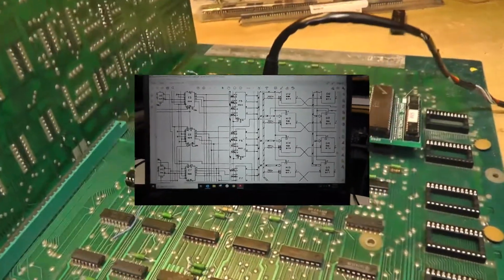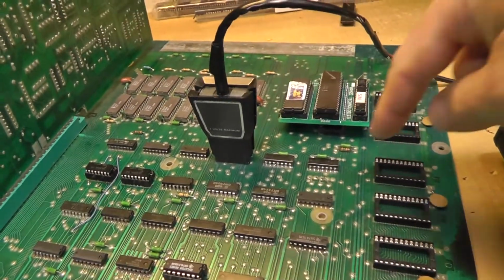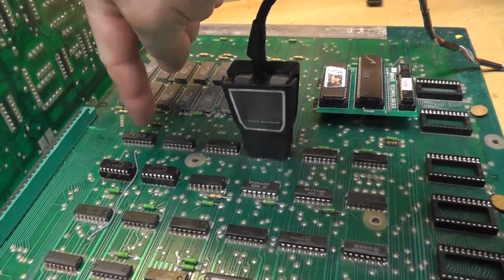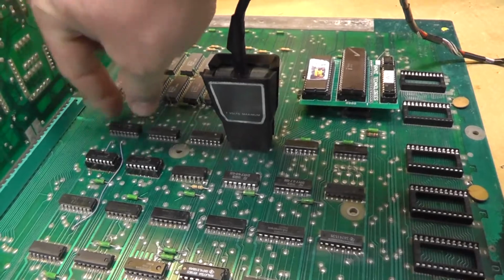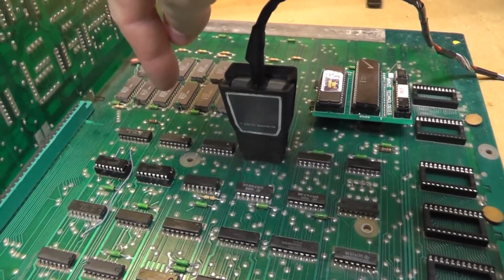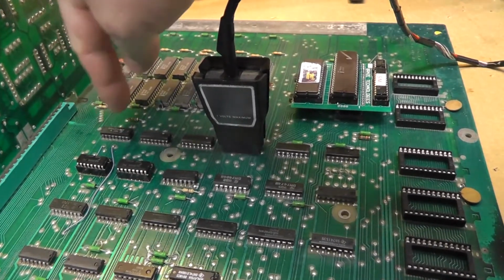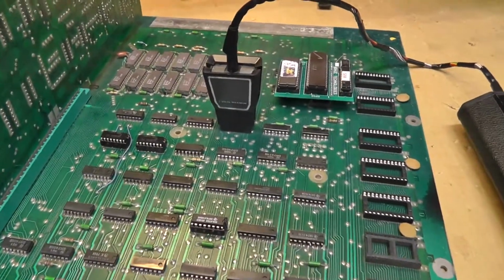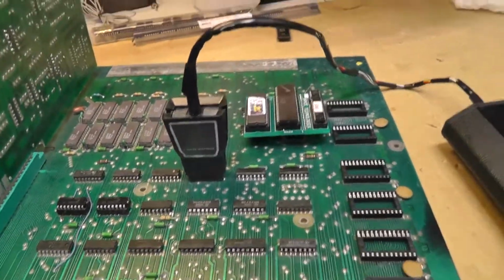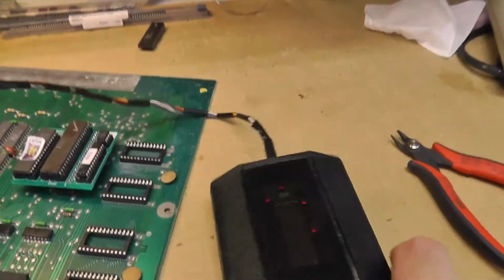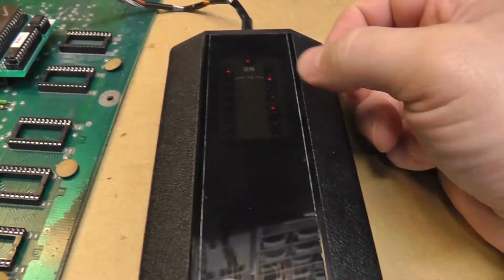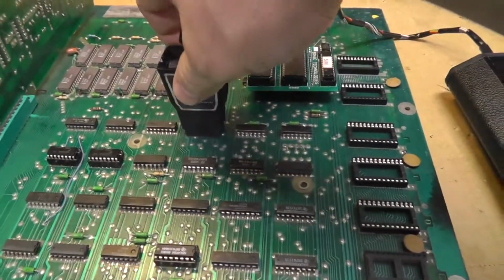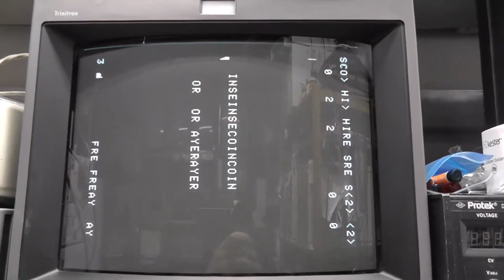So I basically hooked up my logic comparator. The muxes are at F4, 5, 6, and 7, and F7 was replaced previously. I can look underneath it and tell. It is a 74LS157, whereas these other ones I believe are the 9322s. And if you see here, on this F4 chip, outputs 4, 7, and 9 are all bad, and you can see it's still got bad screen stuff going on.